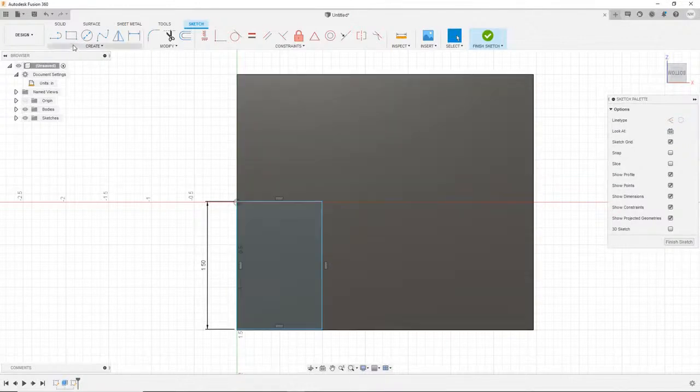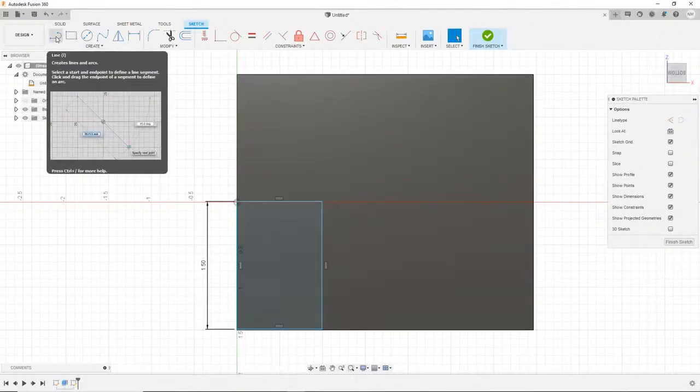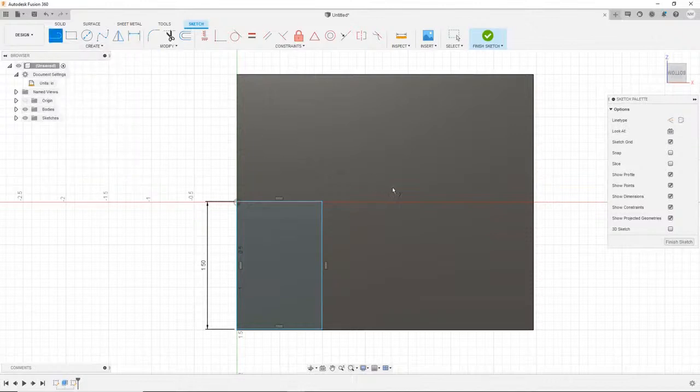Let's now grab our line tool, going back to our Sketch tab, left click. Let's place our line here, left click. Notice the vertical inferred constraint active, so I'm going to left click. Left click, left click, and let's close this profile. Left click. Let's now select our sketch dimension. Left click. Selecting this line and this line. Distance to be 1. Hitting enter.